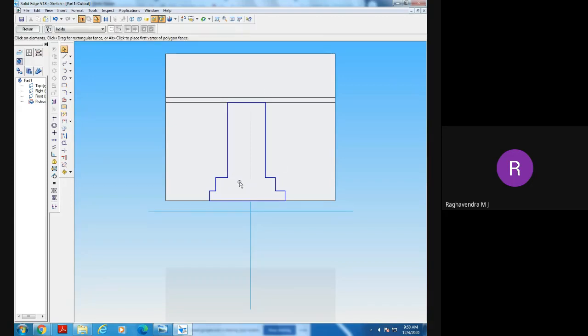Now, as I told you before, before giving the dimensions, we need to apply the symmetric relationship here. That is easier. Go to symmetric axis and select this. Now go to symmetric relationship. These two are symmetric with respect to this one, and these two are symmetric with respect to this one. And these two are symmetric with respect to this midplane. Once again I will show you. After constructing this, go to symmetric axis, select the vertical plane. About that, this profile is symmetric.